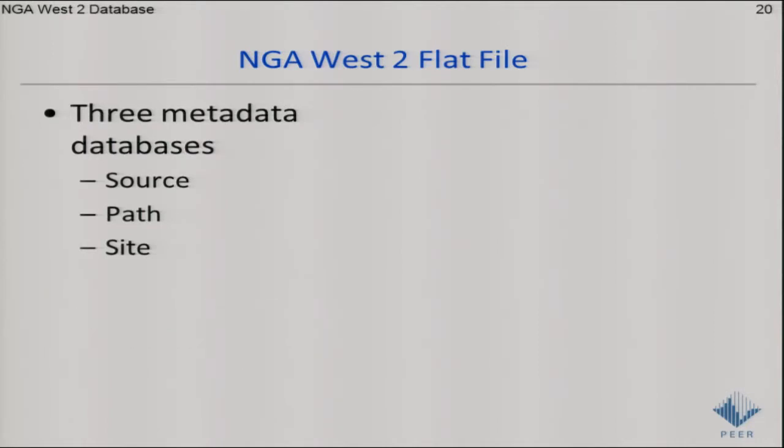And also, there was a large effort to update that information. So if there was a station that had an inferred VS30 value based on, say, geology, and that station has a VS profile, we updated that VS30 to have a measured value. Just using that as an example, we did this for many of the other different metadata that's included in the site database. So this was a major effort.